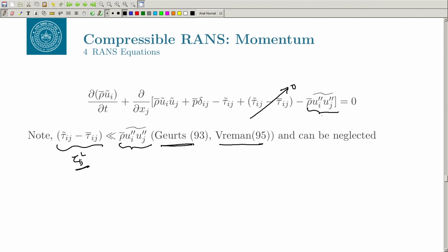The additional term that we have, we will call it Favre stress, maybe not Reynolds stress. So, you can denote it as tau ijf. Earlier we had denoted tau ijr, or tau ij3, which is the turbulent stress, minus rho u prime v prime bar, and now we are denoting it as tau ijf, which can be written as minus rho u prime v prime, the fluctuations, rho bar u prime v.